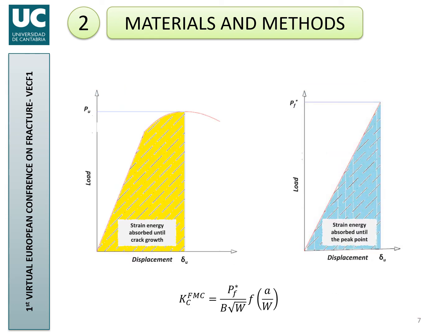Something very similar is required for the fracture behavior. On the left side, we have the real behavior of the material in terms of load displacement curve, and we have to substitute this behavior by the one on the right side, on which the displacement at failure is fixed at delta U, and we have to change the slope till the areas are exactly the same. In this second curve, we obtain the theoretical failure load, this PF star, for the fictitious material.